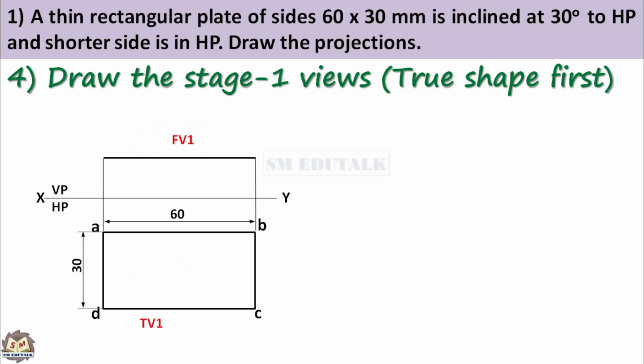To do this, either you can imagine the plate in 3D, that is 3-dimensional, or use these orthographic 2D views directly. You know that in 3D, you get the front view when you look at the plane ABCD standing in front. In 2D, you get the front view when you look at the top view from here. You can see the rectangle's front corner points D and C.